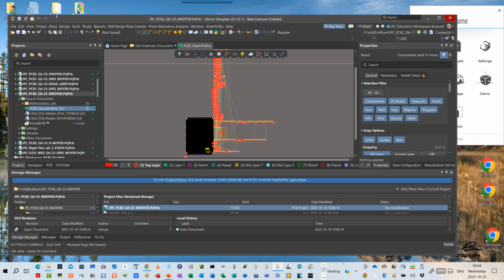I have some mechanical switches on here, so I'm just going to tell the assembler, hand assemble, hand solder these 5 switches onto the board because they're through hole, after the board's gone through the regular washing process. That way they only have to do a local cleaning of those couple of solder pins. So yeah, these are all decisions and notes that we will put on our drawings, but it will be the assembly drawing, not the fabrication drawing.